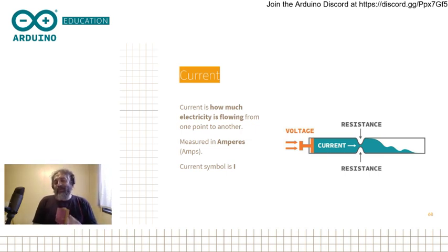This is like this for more or less all of the digital logic. Digital logic is not really meant to drive motors. It's just meant to do logical operations, and then you're supposed to build something in between. So you basically play with voltages inside digital technology. And when you want to reach a certain current to affect the physical world, you need to use something else, which we call a driver.